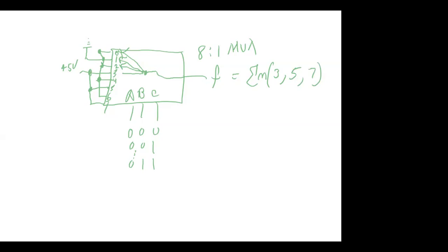How's that grab you? So the MUX is kind of a convenient way to go in terms of implementation, because the only thing I needed was wire, and I got a truth table, which is cool. And as it happens, you can find these in the stock room, and there are a number of variants on it, but I believe it's 74151.